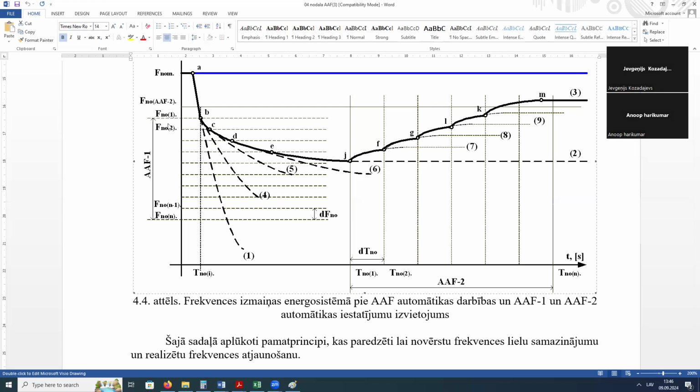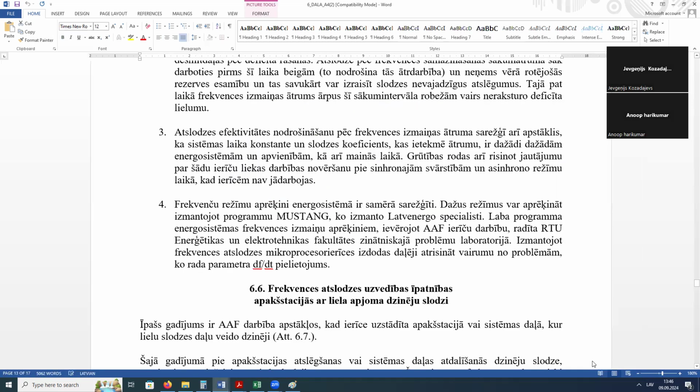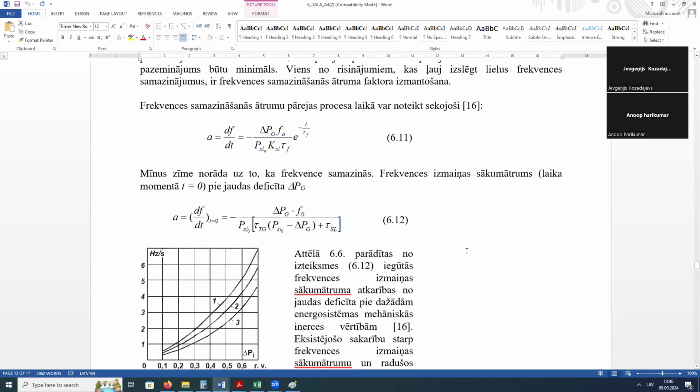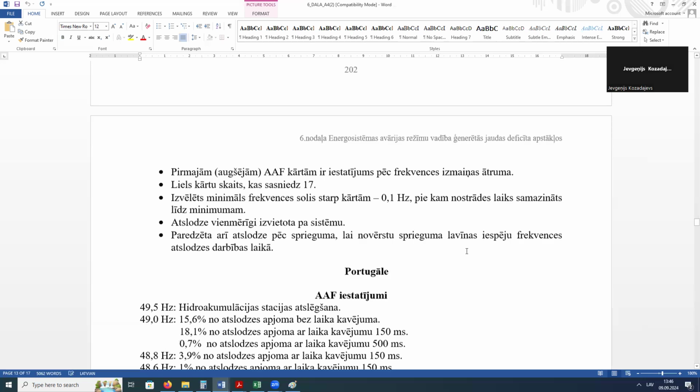That's why we have n stages, about 18 stages here, yes, of set points, and every set point has the same load power for disconnection. In different countries, of course, they have different experience, negative experience, and they have different structure, how this works.